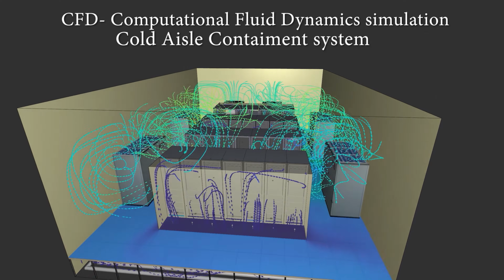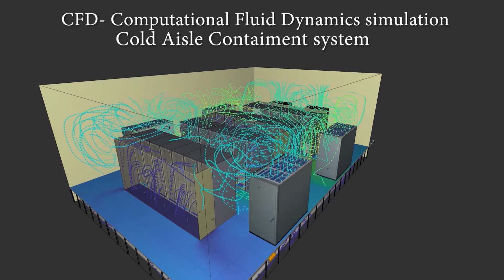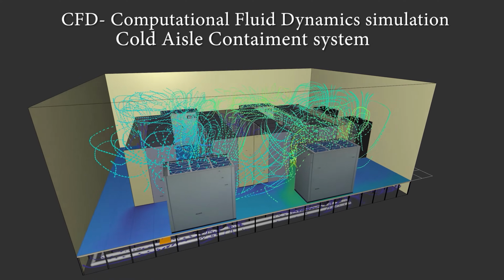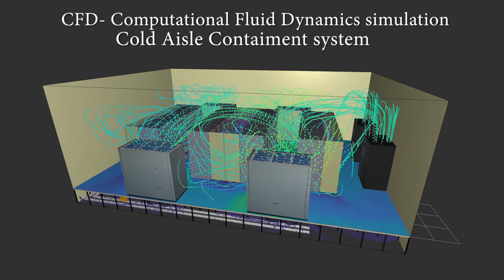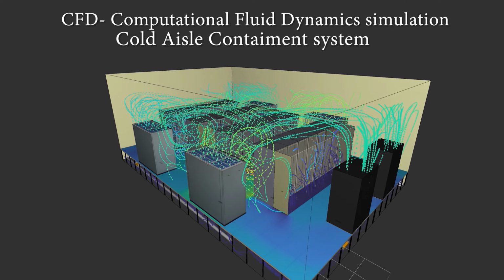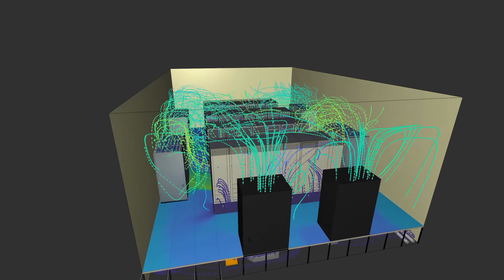Air from the hot aisle mixes with room air and is delivered to cooling units via open return paths. Using cold aisle containment prevents warm air from mixing with the cabinet inflow, producing a more consistent and cooler air supply, compared to a solution that does not use cold aisle containment. However, the temperature within the remainder of the room can exceed the allowed working temperature.